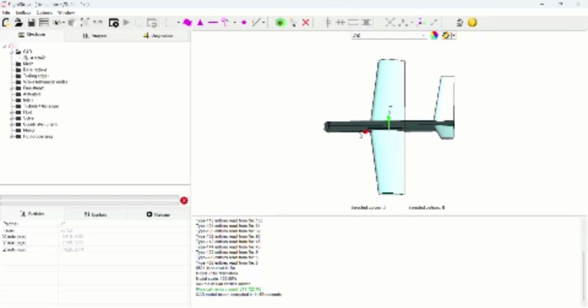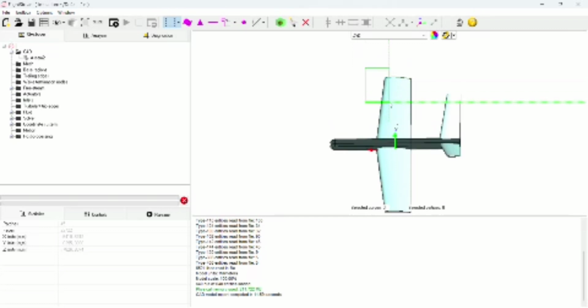First we will take the model and cut it down into different parts, such that our simulation will be much simpler and can be done on various parts with separate loads or boundary conditions. So we'll take the lasso tool and select the wing. First, using the rectangle lasso tool, we'll select the wing.